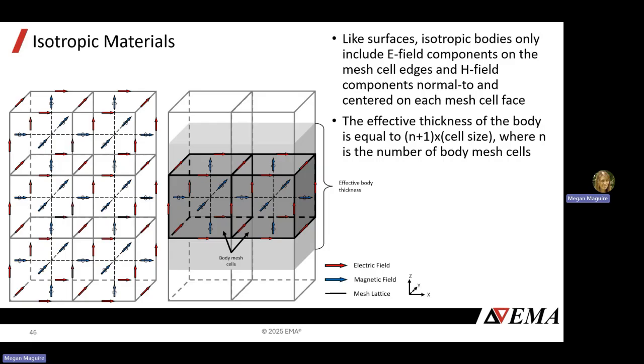So that's one thing to keep in mind when you're doing body meshes. In that case, you would want it to be only 20 millimeters thick in your model to have it actually be 30 millimeters thick for what the solver sees.